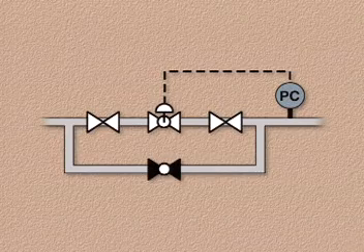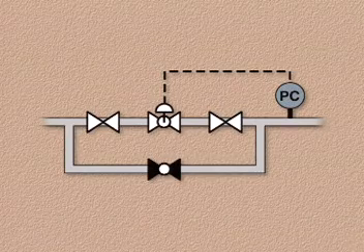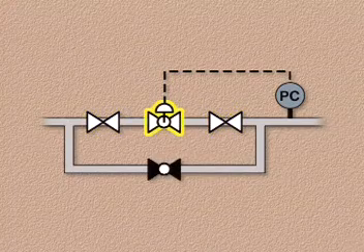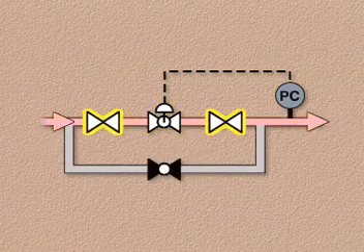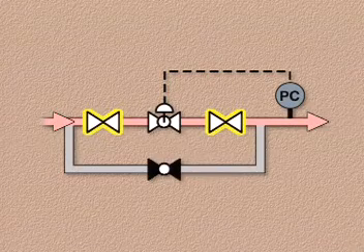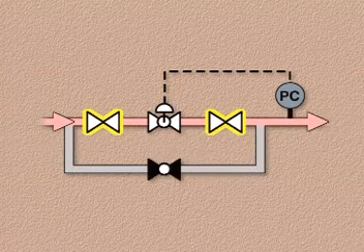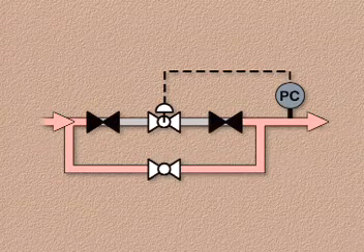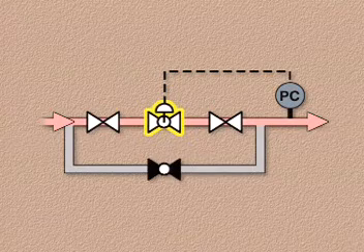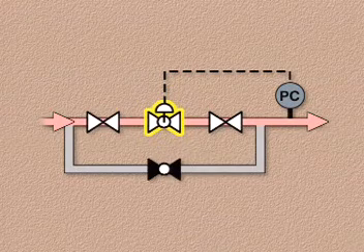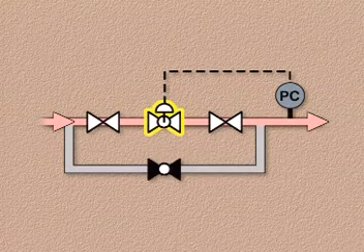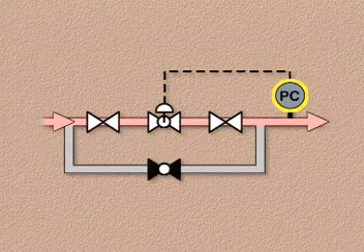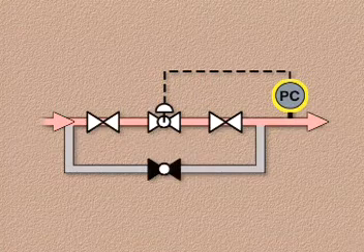In our example, the pressure regulating branch of the control system contains two manual gate valves and a pneumatic diaphragm-operated control valve. The gate valves are isolation valves. They're open during normal operation, but they can be closed if necessary to isolate the branch from the steam supply source. The pneumatic diaphragm-operated control valve is a globe valve that is used to regulate pressure.